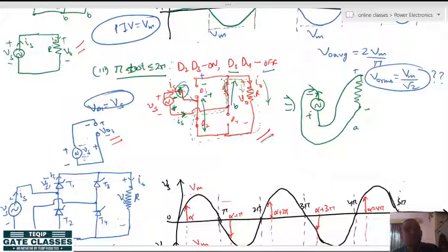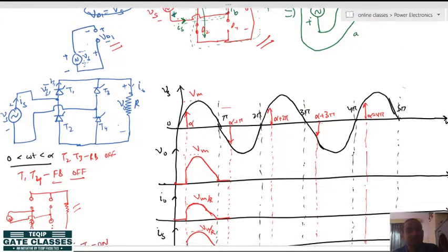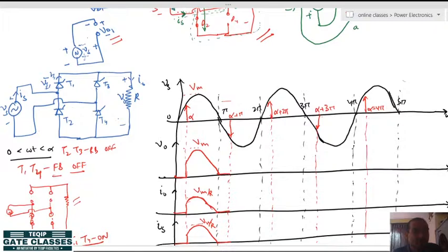which we have drawn in the diode case. All right. So now in this case the circuit will be like this. Again you see that when T2 and T3 are on, the supply is this, so the current will go like this from here to T3 to load, and then load to T2 and T2 back to supply. So here you can see the load voltage reference is again followed and load current reference is again followed. Hence, again the load is in parallel with the source and the reference is followed, hence it is positive. All right, and the load current will also be positive.